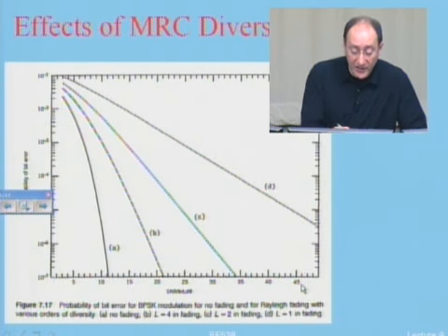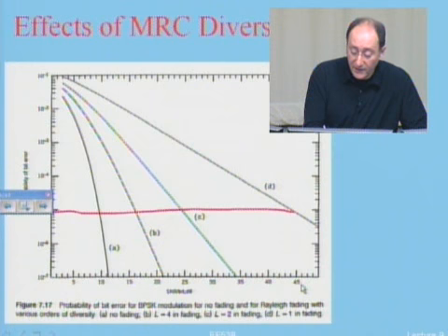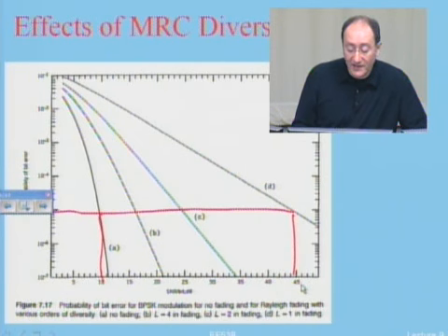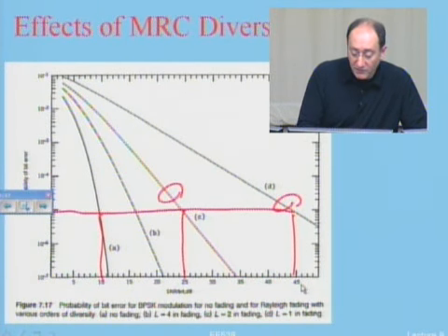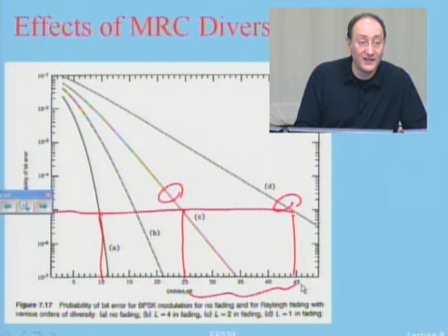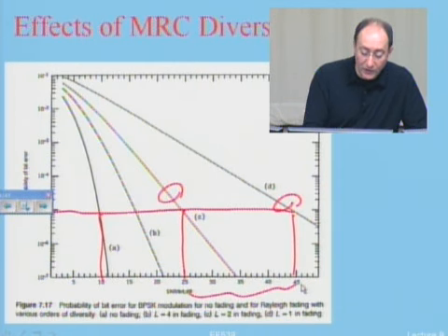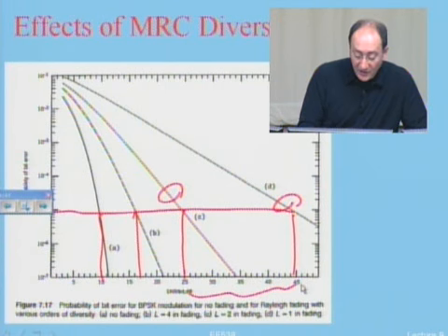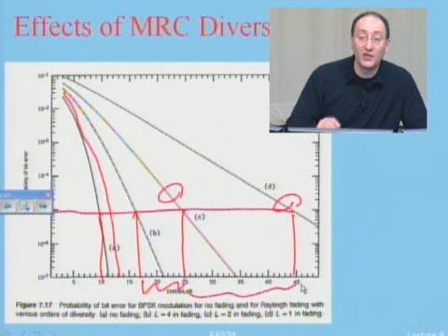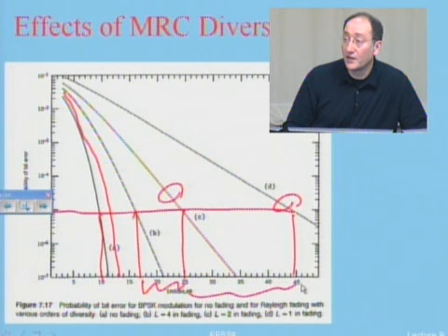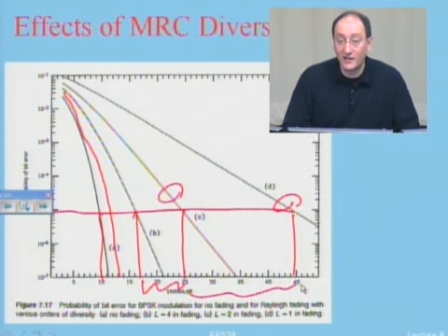But if I now create, like, this is 10 to the minus 5, and this one and this one. This we had last time. But if I go from fading channel to 2 order of diversity, I save like 20 dB. And then if I put like 4 antennas, I will save another like 10 dB, close to 10 dB. If I have 8 antennas, my performance gets very close to non-fading. Okay, so my objective, I mean, what I showed you last time, this is the summary.